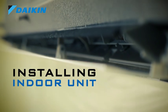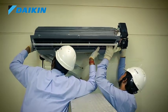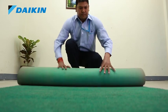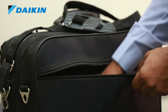Installing indoor unit. Let's understand the step-by-step procedure to install the indoor unit. Before starting the work inside the room, remove any carpet on the floor to prevent it from being damaged. Take out the plastic sheet from your bag and spread it on the floor.